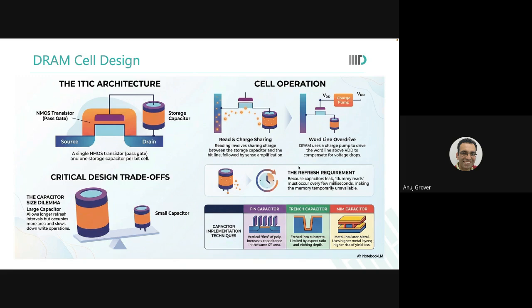As it shifts to the right, the current that flows when gate voltage is 0 would reduce, even if the sub-threshold slope remains the same. And therefore, we want to somehow increase the VT of the pass gate.